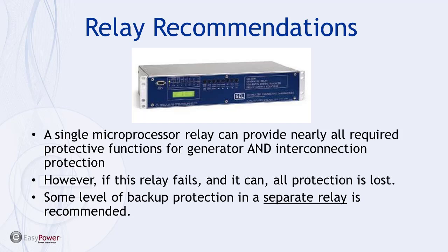Ideally your backup relay would connect to a separate set of CTs in case the CT fails. But one way or the other, you do really want to have a backup relay of some type.